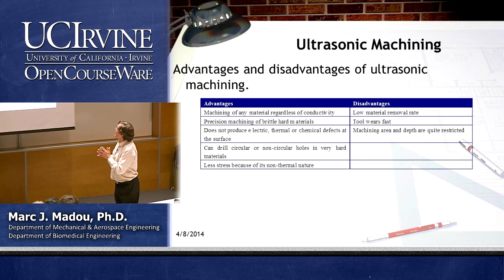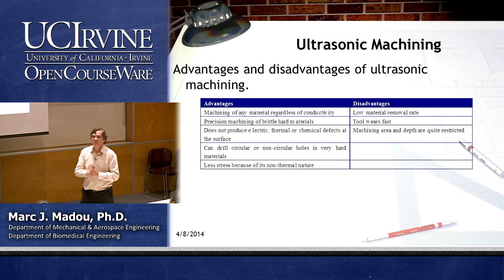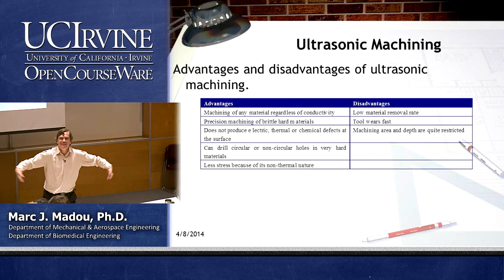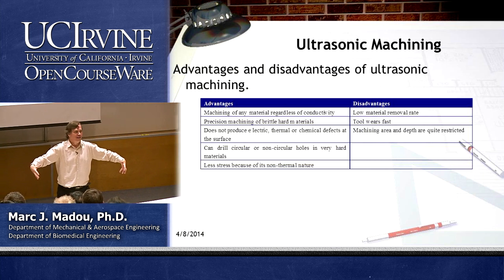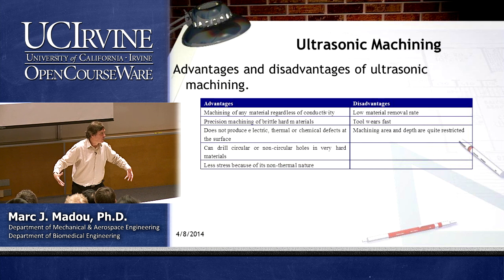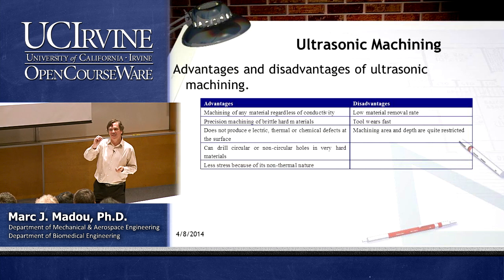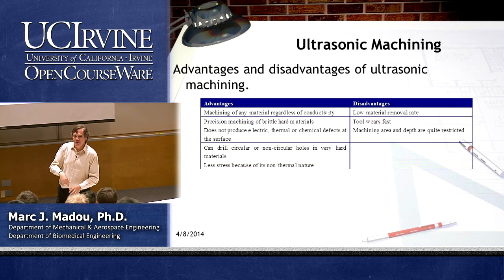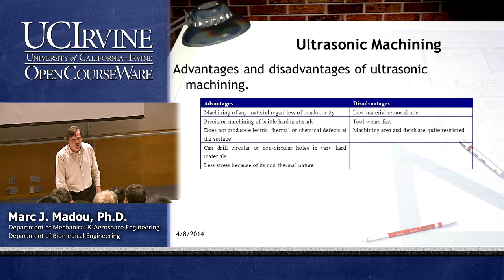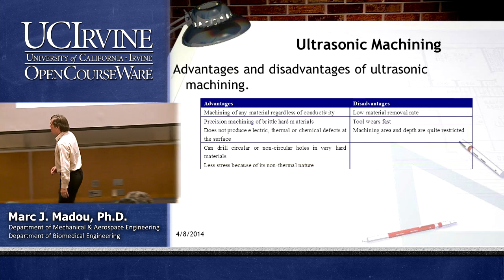And then machining area and depth are quite restricted. So you can imagine, you cannot make a very big ultrasonic tool because the power you would need to bring this thing up and down just wouldn't apply, right? And the depth also, yes, you will not drill very, very deep holes with that. So with this,